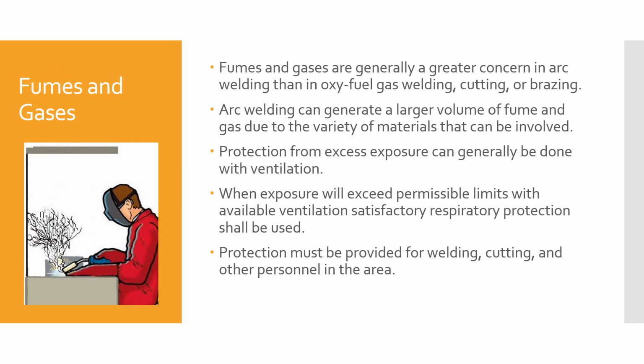Fumes and gases are generally a greater concern in arc welding than in oxy-fuel gas welding, cutting, or brazing. Arc welding can generate a larger volume of fume and gas due to the variety of materials that can be involved. Protection from excess exposure can generally be done with ventilation. When exposure will exceed permissible limits with available ventilation, satisfactory respiratory protection shall be used. Protection must also be provided for welding, cutting, and other personnel in the area.